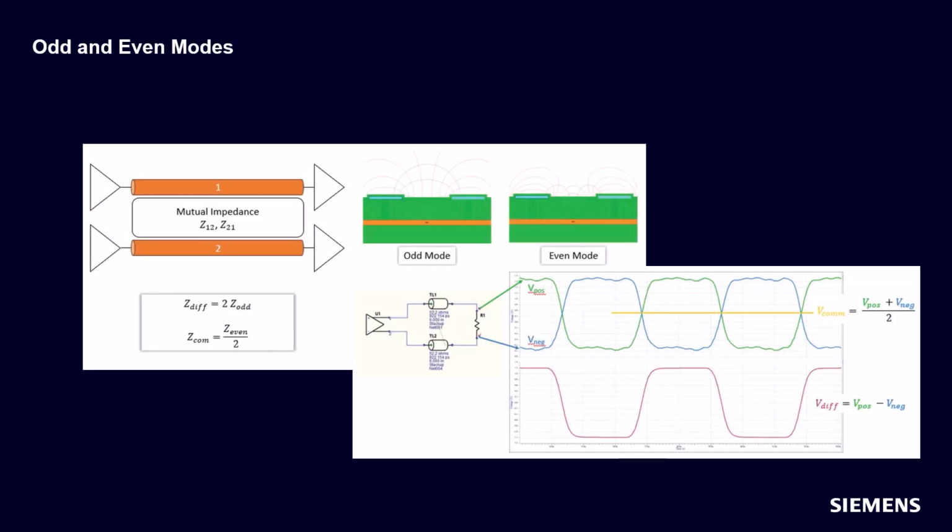This illustrates that when elements in the differential channel become imbalanced, perhaps due to mismatched lengths or different loadings or asymmetries in the return path, some of the differential signal energy can convert into common mode signal. This is known as mode conversion. When differential energy converts into common mode, the pair loses its symmetry. Both traces effectively carry the same voltage or current instead of the desired equal and opposite signal. This makes the pair far more vulnerable to external noise, increased EMI radiation, and can cause increased reflections and jitter.